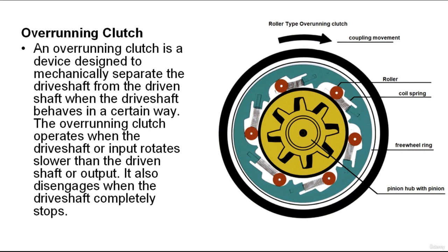The roller clutch is designed with a movable inner race, rollers, accordion springs, and outer race. Around the inside diameter of the outer race are several cam-shaped pockets. The rollers and accordion springs are located in these pockets. As the vehicle begins to move, the stator stays in its stationary or locked position because of the difference between the impeller and turbine speeds. This locking mode takes place when the inner race rotates counterclockwise.